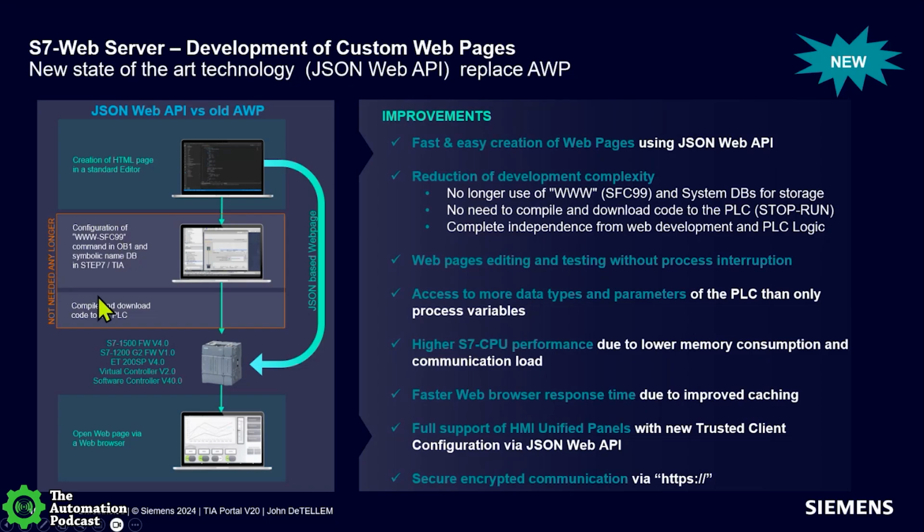Basically, it's showing the old way of creating some data blocks and OBs in the PLC that contain the look and feel of the web page, and now we're fundamentally evolving that to where we support more functionality. So it opens up the controllers, in this case, to provide another layer of diagnostics beyond what might be configured with the system diagnostics or the ProDiag to the HMI, or allow you to create your own user-defined web page that could be powerful for managing quality or maintenance of the PLCs for your specific application.